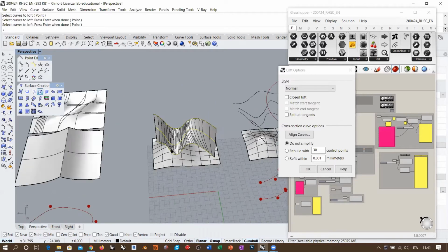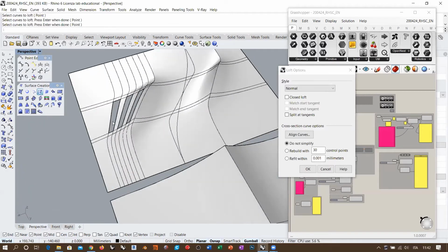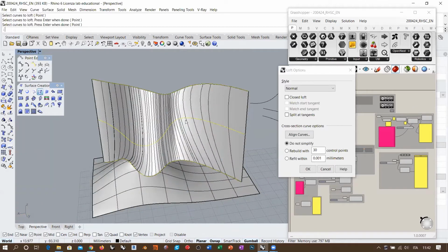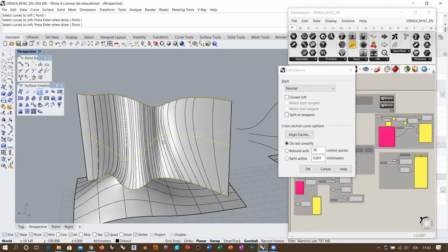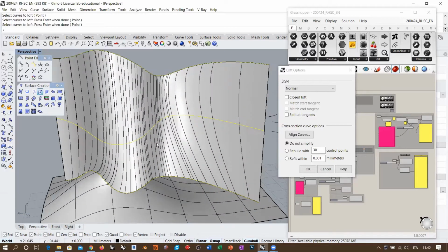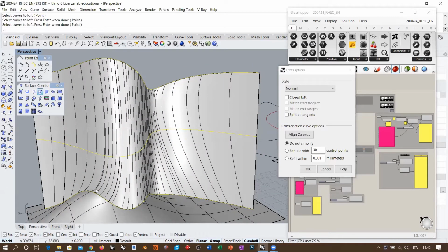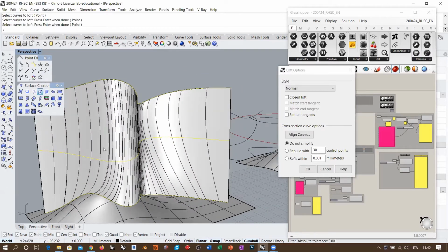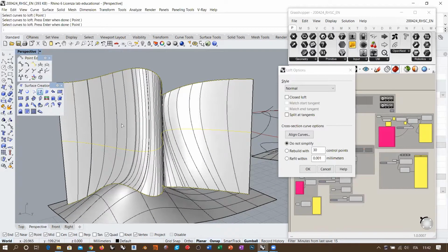First one, for example, would be these nice cuts that we created here that were perfectly aligned with the isocurves, because the isocurves depended on the topology that we were controlling. Now we are not controlling topology here because this is an automatic interpolation. So if we try to extract isocurves, this is the behavior that we are going to get. If we want vertical holes or cuts, we cannot do this by simply extracting isocurves because they will come bent like this.